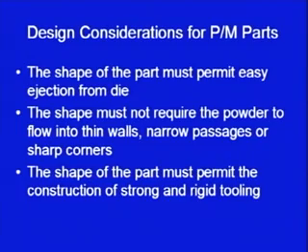First of all, to make a die which has narrow passages and thin walls is a difficult task. The next point is that getting the metal powder, or the blended powder mix, to enter these thin sections or narrow passages is itself a difficult task. One of the important properties of the metal powders that we have discussed is flowability. So, if the metal powders do not have adequate flowability, the powdered metal will not be able to enter into the thin walls or the narrow passages.